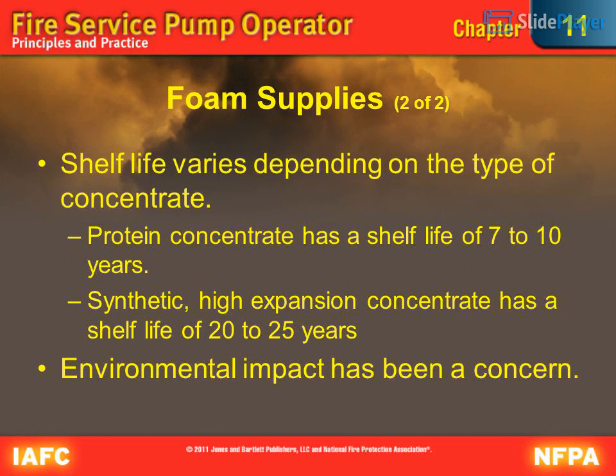Foam supplies, 2 of 2. Shelf life varies depending on the type of concentrate. Protein concentrate has a shelf life of 7 to 10 years. Synthetic, high expansion concentrate has a shelf life of 20 to 25 years. Environmental impact has been a concern.